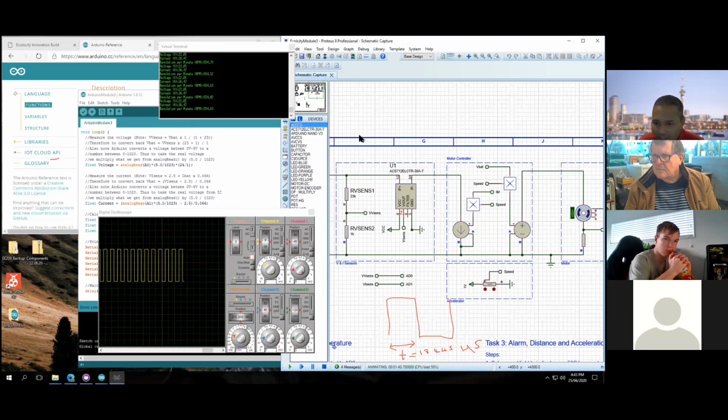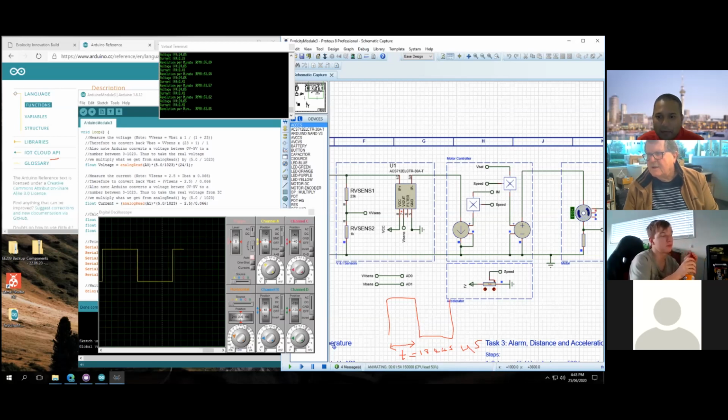Now if you want to slow it down, let go of the accelerator. Current goes negative first. Why does the current go negative when you start braking? It's feeding back into the battery. Yeah. So it's called regenerative braking, and that's why some electric vehicles are really efficient.